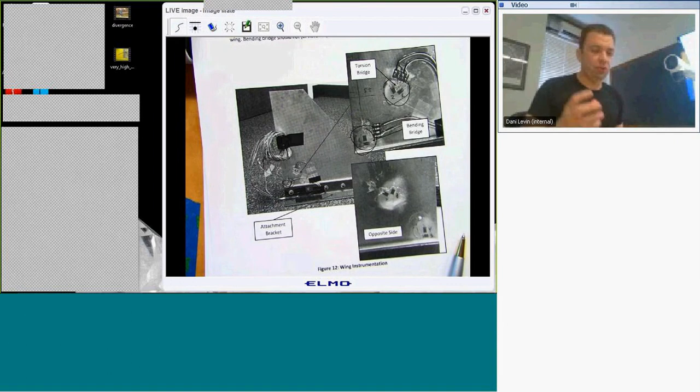If you buy a strain gauge based load cell, inside you have your Wheatstone bridge. A Wheatstone bridge has 4 wires: 2 wires are V in, you feed the circuit, and the additional 2 wires are V out.